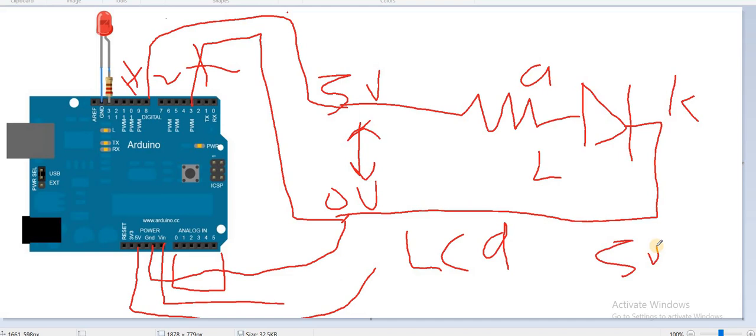Actually, we'll be talking about voltage regulator in the future. So you just supply this 5 volt to the module, and if you're using some other components or other module or other things that you want to be using with the Arduino board, just connect. If they're using 5 volts, connect the 5 volt pin to the module.